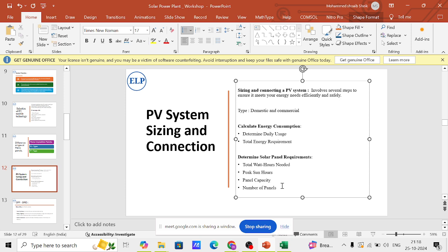So now, the number of solar panels required for 4.5 kilowatt: if you're using 500 watt, you just divide it, or if you want to go with 250 watt solar panels, whatever the type of installation. If you have a large space on the roof or on the land, you can go ahead and install lower wattage panels like 250 watt. If you have very little space, you can install higher wattage, that is 650 watt solar panels, right? Is that fine for you, everyone? Are you getting this?